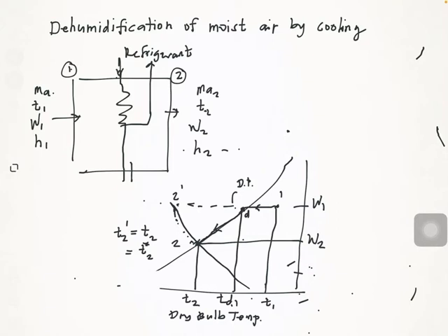The process may be interpreted in 2 ways. For the moist air system alone, the process proceeds at constant humidity ratio from 1 to D and down the saturation curve to 2. For the total system of air and condensed moisture, the process is one of constant humidity ratio from 1 to the fog condensation at 2 prime.